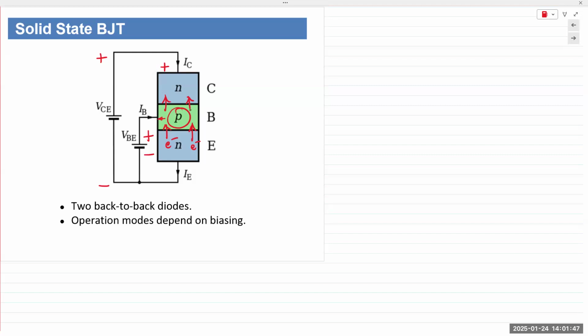In an N-type material, electrons are the majority carriers, holes are the minority carriers. And so technically, we would say for an NPN transistor, electrons are the majority, and holes would be the minority. But when it comes to type of semiconductors, it's just simply P and N type. And then for a PNP transistor, holes would be the majority carriers.